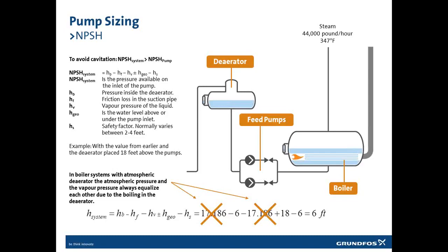Okay, great. So if we are running a 150 psi boiler at 75 psi, we still need to size the pump for the 150 psi. And also at the flow rate of the boiler nameplate horsepower. Yes, exactly. So further justification for speed control, because then you can right size your pumps. Exactly. Okay, that's all questions so far. Which pump to choose?